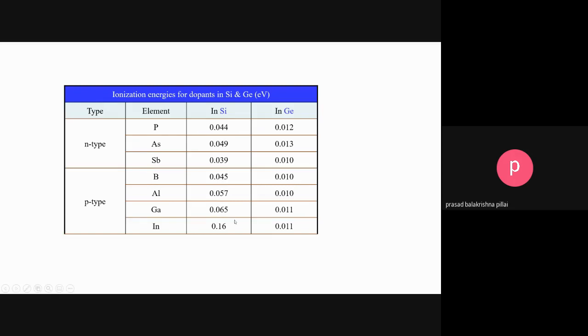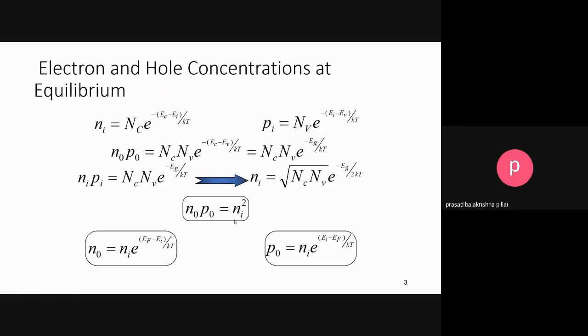So anyway, going back, with that for the intrinsic semiconductors, this is the expression for Ni, the intrinsic carrier concentration. Nc stands for the density of states in the conduction band, and then this is the probability function. This is actually the Fermi function approximated to Maxwell-Boltzmann distribution, because we are considering a non-degenerate case where a large density of states is available in the conduction band. So this is Ni.